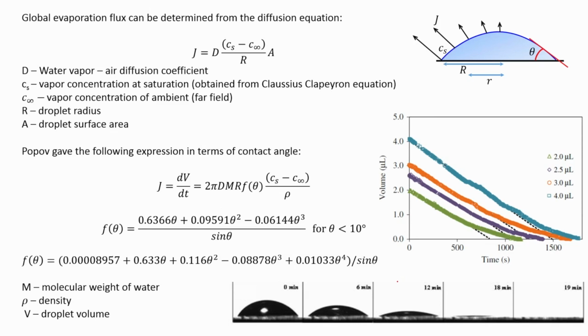Now, you can see that the evaporation flux is highly non-uniform across the surface, right. It is very high at the edge, very low at the apex, right. So, it is very unlike the spherical contact free droplets that we dealt with so far, where it was very isotropic, correct, and the flow was also diverging, going radially outward, right. So, these are the few things that you can get from your hydrophilic droplet.